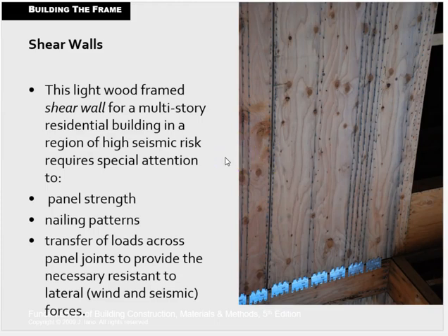And then shear walls. So that was tie downs in the previous slide, and now shear walls. This is what keeps the building from racking, essentially, by resisting the wind that's blowing on the side of the building. Again, here in Philadelphia, the plywood on the outside would suffice to resist that. The frame without plywood could move pretty easily left to right, and we call that racking. Once you put the plywood on it, it will not do that.